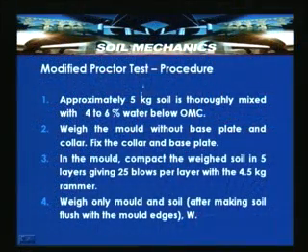So, by giving this 4.5 times extra energy with the modified Proctor compaction test, it is possible to compact the soils as close as possible to the maximum possible position and expel the air quickly, so that maximum dry density can be achieved at the possible low water contents. The procedure is similar to the standard Proctor compaction test. The differences have been discussed already.